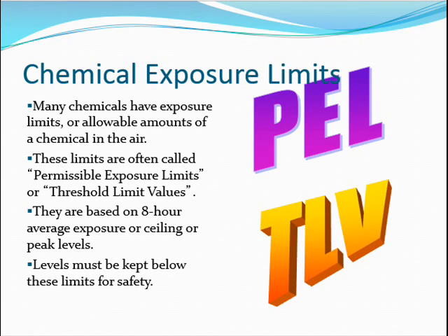Permissible exposure limits, also called PELs, and the threshold limit values, which are called TLVs. OSHA regulations have PELs for about 600 chemicals. The limits are usually expressed as parts per million or milligrams per cubic meter. Your exposure to the chemical should never exceed these limits.